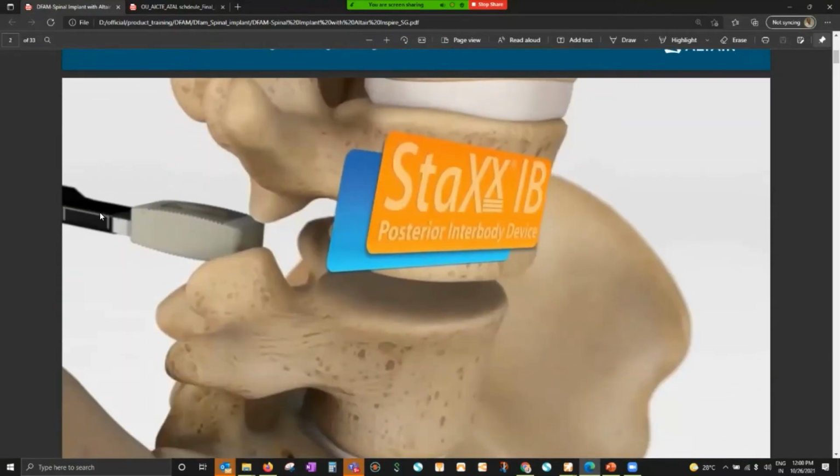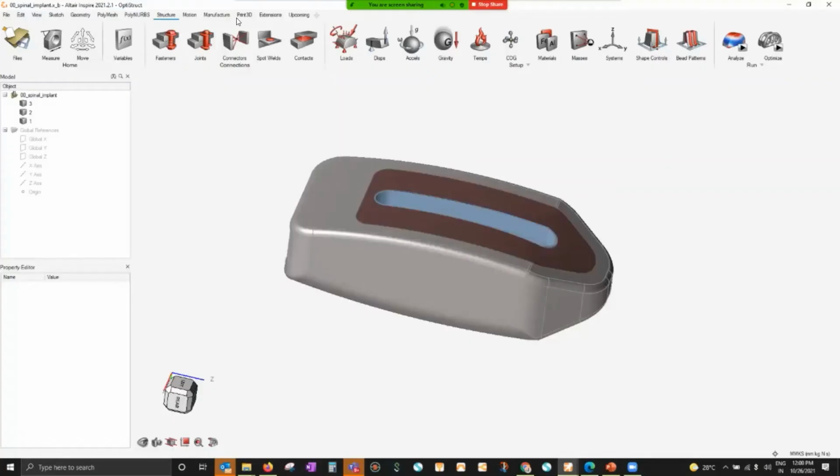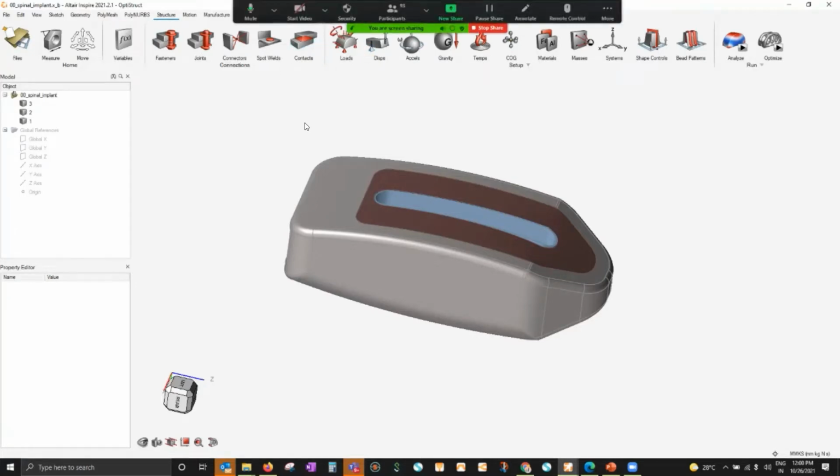That means in the field, which are the areas where the load and restriction will come. So you have to explain that to the software, and the way you explain it is through what is called loads. There is this loads icon available under the structure tab. And from here, you have to select the right tool to define those loading conditions and restriction conditions.